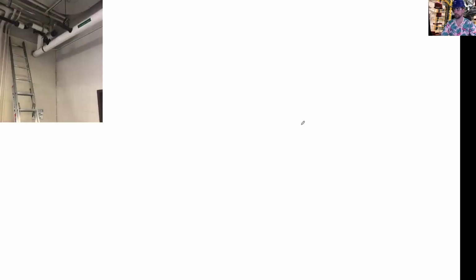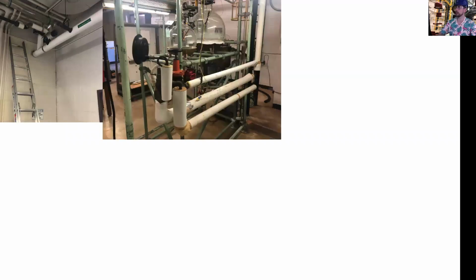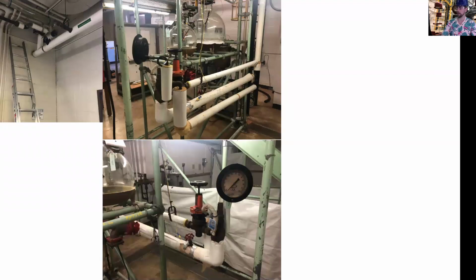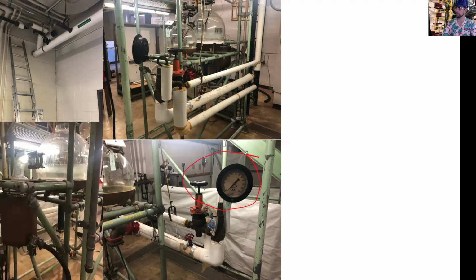Once that's all done and you have everything ready, you turn on the steam, which, if you're walking in the lab, is in the upper left-hand corner above the dry chemicals room. It's this main valve right here. And then the steam comes into the distillation unit through these pipes behind it, and you control the PSI right here. Make sure to stay within the bounds of the user manual that's located there.